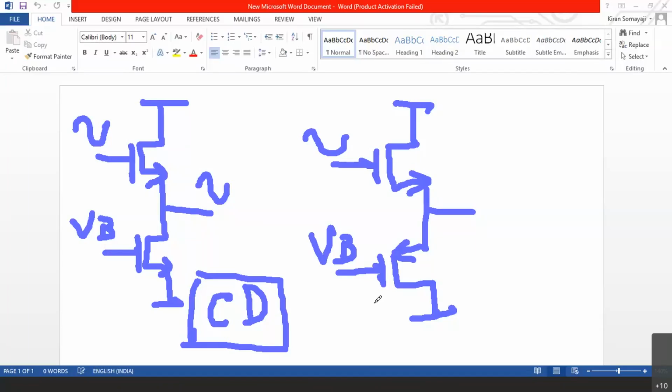It is as if it is analogous to, instead of using NPN transistor BJT for emitter follower, we can use PNP also as emitter follower. But the connections are in a reverse way. Similarly, it is not necessary that common source amplifier has to be always having PMOS at the top for resistor and NMOS at the bottom as an amplifier transistor. We can use the other way also.